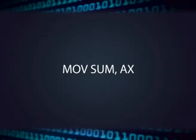In all memory reference move instructions, the effective address of the memory location is computed as the offset specified in the instruction, added to the contents of the data segment register, which is shifted left by 4 bits to make it a 20-bit address. Take an example where the instruction is move sum, AX.